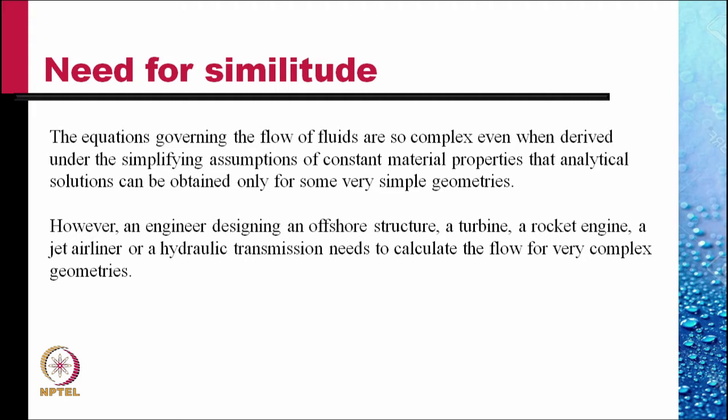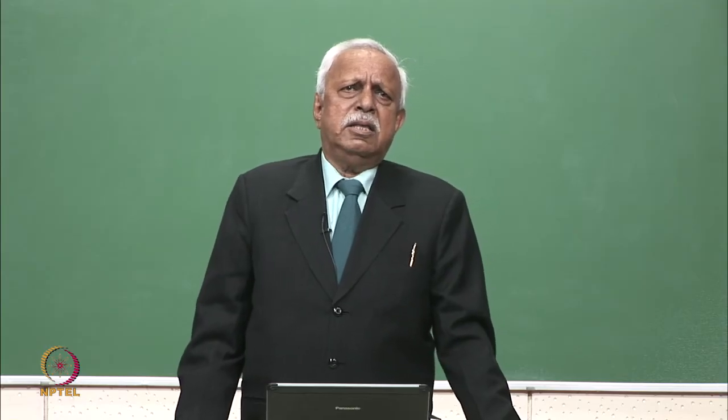it is possible to do experiments on the actually designed structures, but there are problems. Sometimes the structures are so big that if we make them in the first place without testing, we would not know whether they'll work or not, and that calls for too much investment. So, it is always advisable to test them in models. But how do we test them on models? What rules of model making should be there, and how to interpret the results of the model?